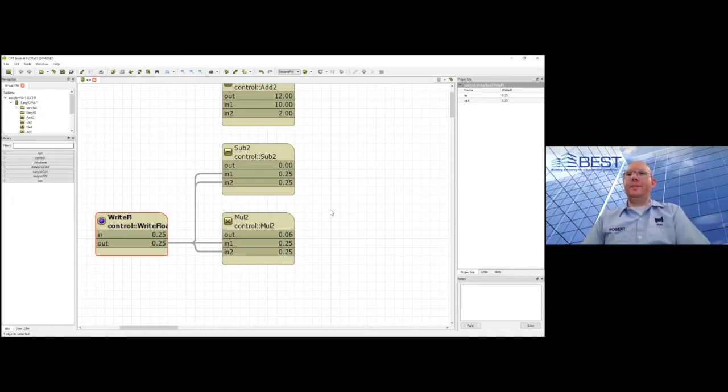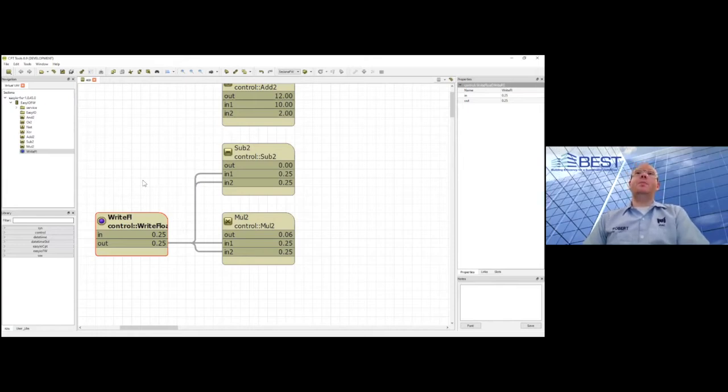There's a solution to that because the Contemporary Controls system doesn't actually give us access to a square root function. EasyIO does, so we're going to do that one first. It's all involved with installing a new library, which is a basic task in the EasyIO system. Contemporary Controls has most of the libraries installed already, but there are a couple you can still install. This is a very important task. We're going to do it a couple of times today, doing different libraries.